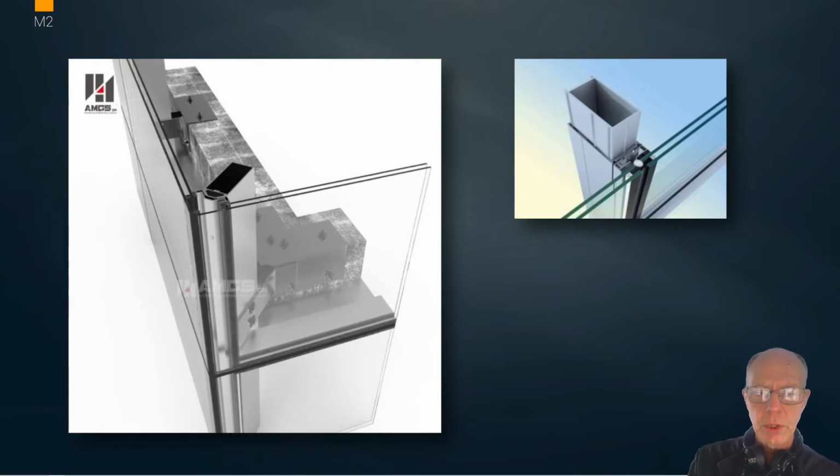Glass is going to be a really important subject for you to deal with as architects. There are so many variations in the way that you can apply glazing systems to the exterior, and nuances to it that can radically affect the appearance of your architecture. For instance, what happens at the corners, whether it looks like a continuous piece of glass or whether there's a piece of aluminum interrupting that.